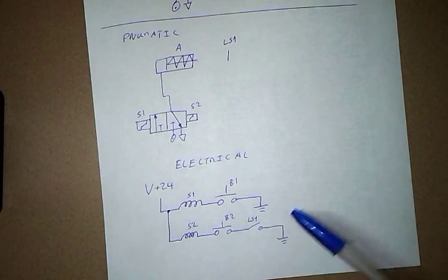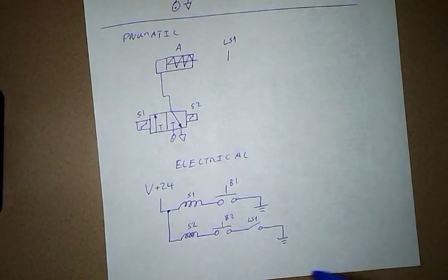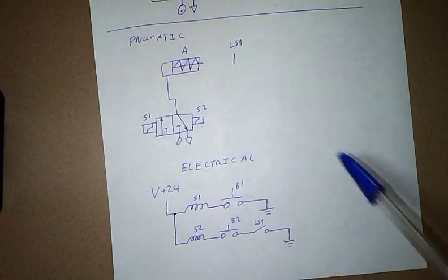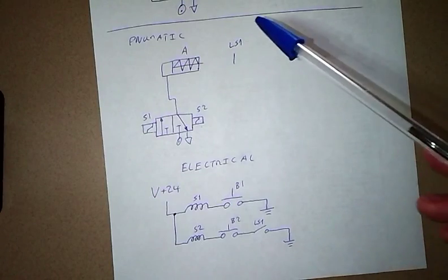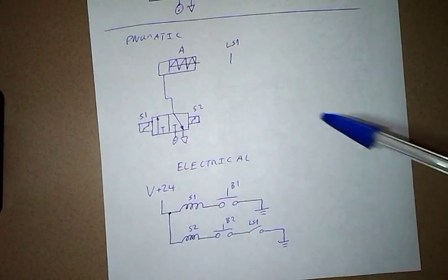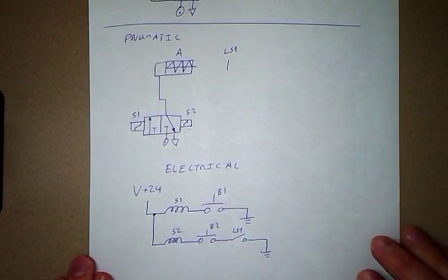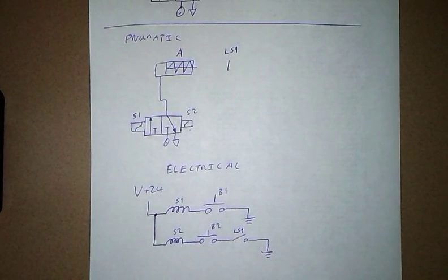Okay. So this combination of pneumatic and electrical diagrams provides the functionality that we want. Whenever we press a button, the cylinder will extend, and whenever the cylinder is fully extended and we press another button, the cylinder retracts. So these two examples show the combination of pneumatic and electrical diagrams and how this is made possible through labeling different components. And we'll go over a little bit more detail in electrical circuits in the following videos.